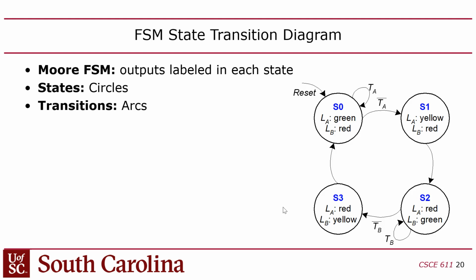and then you have this unconditional transition that comes into this state where we've switched now academic to be red and Bravado to be green, and we'll stay in that state for as long as there's traffic on Bravado. And in the instant there's no traffic on Bravado, we'll switch Bravado to yellow, academic to red, and stay in that state for 1 cycle, and then go back to green light on academic. Does that make sense? Okay, so it's a really simple state machine.